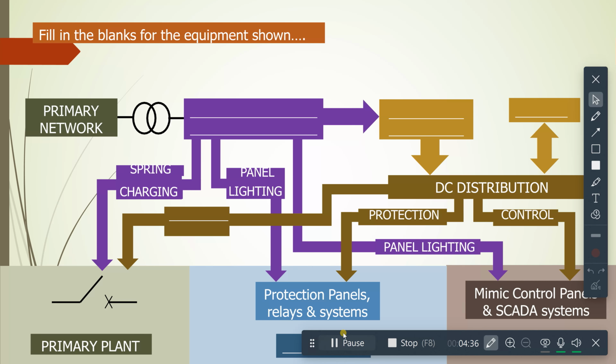So we have three conditions of this circuit breaker. One is when the breaker is closed, and if something goes wrong, then the circuit breaker is tripped by an electrical protection system and it opens the system upstream and downstream. Next is the symbol that we use for the protection relays. The number or symbol inside the rectangle indicates the type of relay as per international standards.